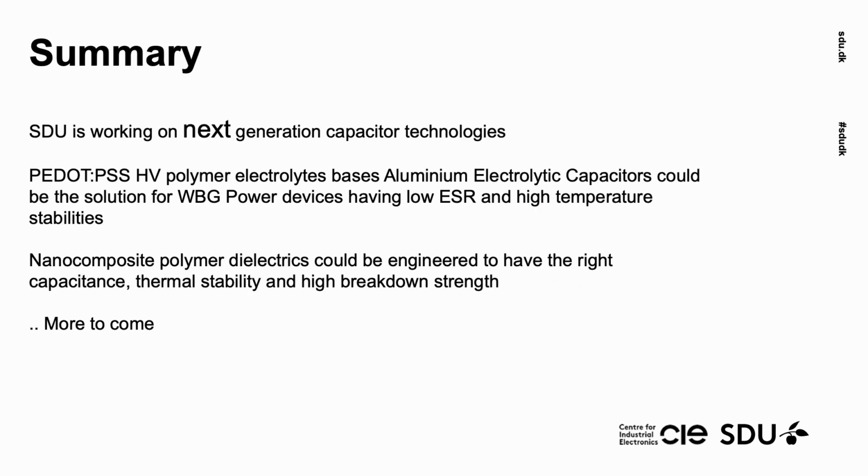I would like to summarize my talk. SDU is working on next generation capacitor technologies. PEDOT:PSS high voltage polymer electrolyte based aluminium electrolytic capacitors could be the solution for wide bandgap power devices having low ESR and high temperature stabilities. Nanocomposite polymer dielectrics could be engineered to have the right capacitance, thermal stability, and high breakdown strength. More to come.